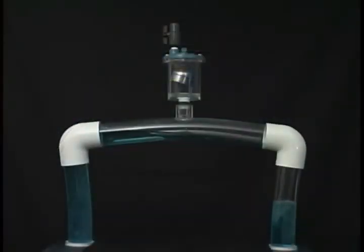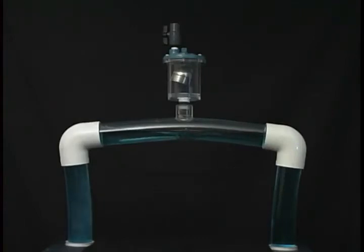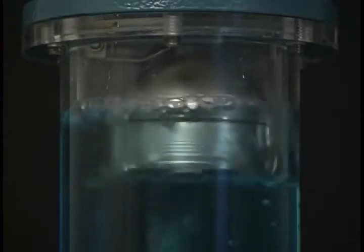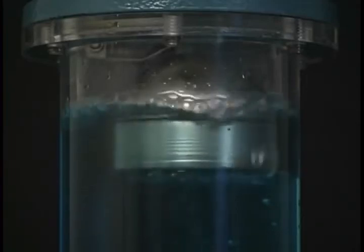Here's a sample pipeline with an air release valve at the high point. An air release valve, sometimes referred to as a small orifice valve, will continuously release accumulated air during system operation. As air from the pipeline enters the valve, it displaces the water, allowing the float to drop. The air is then released into the atmosphere through a small orifice. As the air is vented, it's replaced by water, raising the float and closing the valve orifice. As air accumulates, the valve will continue to cycle in this manner to remove collected air.